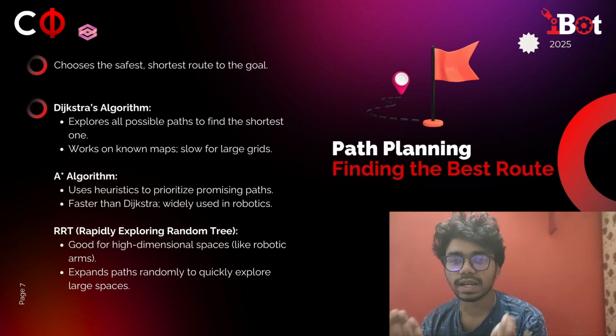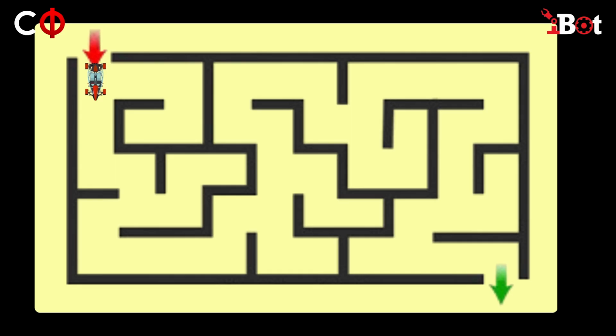Let's, for example, try this maze. Here's the maze. We are trying to solve it with a right follow robot instead of a left follow robot because I feel the right follow robot is more suited for this. So in the right follow robot, we have the priority of first moving right, then moving forward, then moving left. So the priority is as follows. Now the robot moves straight as the right part is occupied, because that is the only way it can go. Now it reaches the dead point where moving forward is not available and this is not available. So it turns right then moves forward.